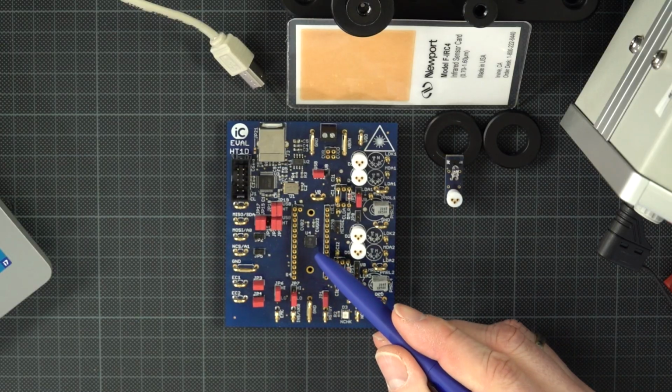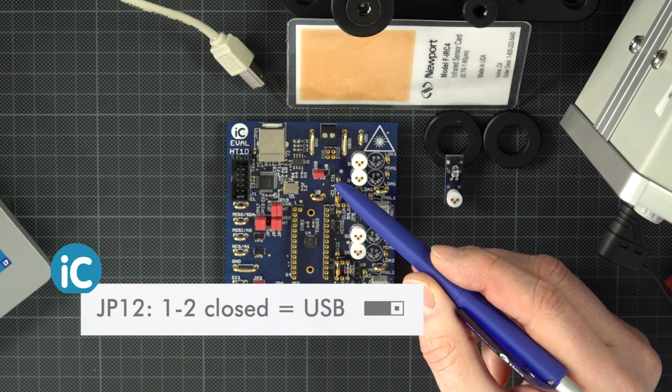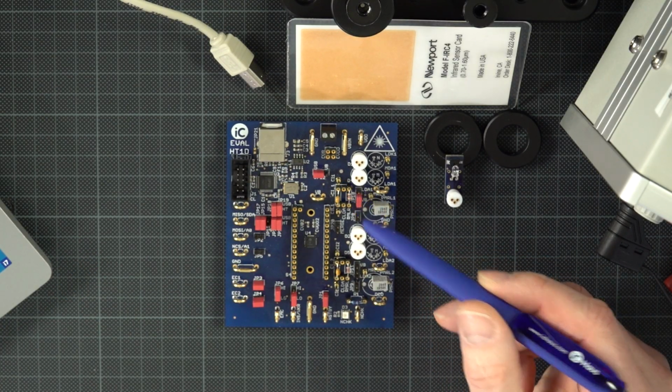The iC-HT chip shall be powered with 5 volts from the USB. So JP12, in the top center of the PCB, goes onto its 1-2 position labeled USB.